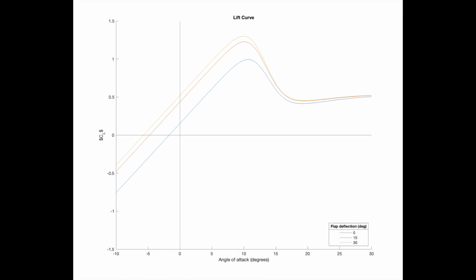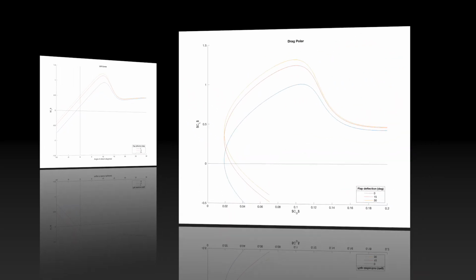First, 3 flap settings, 0, 15 and 30 degrees, are displayed together with the coefficient of lift versus the angle of attack of the aircraft. It is clear that 10 degrees of attack angle yields the highest coefficient of lift for all flap settings. According to the tests, an Albatros can lift as much as 1.3 coefficient of lift when its flaps are positioned at 30 degrees. By contrast, the datasheet indicates that flaps 30 will have a maximum coefficient of lift of 1.4 at an attack angle of 12.834 degrees.